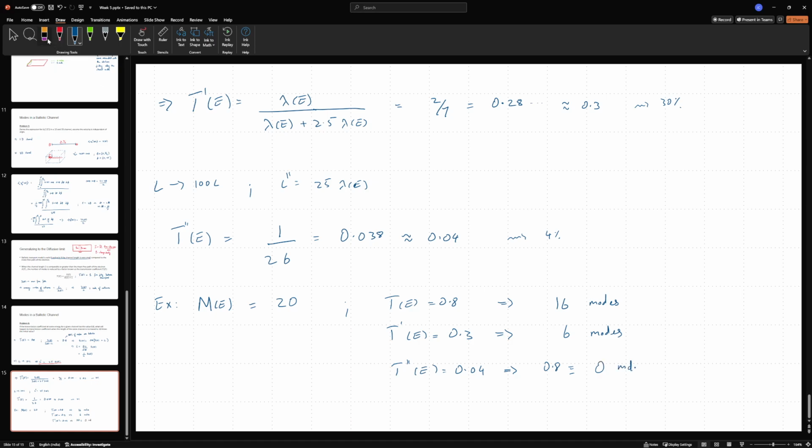So, if I have a channel of this length, does that mean the material stops conducting by just increasing the length? The answer is no. At this point, the only thing we can say is only diffusive transport occurs. Essentially, I can no longer ensure that there is ballistic transport in my material. In fact, I can guarantee that there is no ballistic current, only diffusive current.